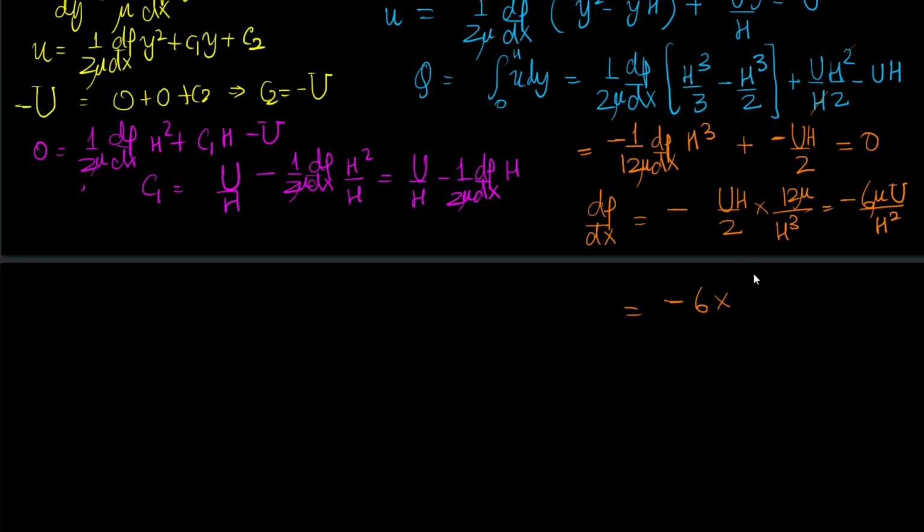The problem mentions that it is at 60 degrees Celsius, so quite naturally it's for some kind of a journal bearing. The viscosity is given as 4.7 into 10 to the power minus 4 Newton second per meter square, times the velocity 0.3, upon h square. The gap is given as 3 millimeter, so it is 3 times 10 to the power minus 3 meter, squared.